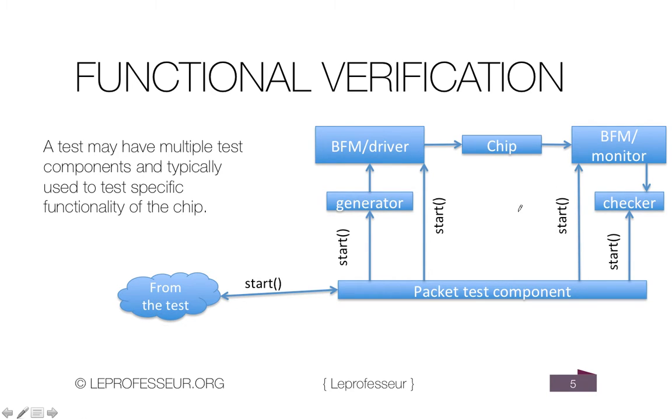and so on. So basically, the verification idea is very simple. Your DUT, okay, now you drive some input and you get some output. Okay. Now how will you check whether this is the expected output? So you should have somewhere in your test bench a similar module which is mimicking the DUT, behaving like the IP under test, and this is also generating the output, and then here you are comparing the output from the chip.